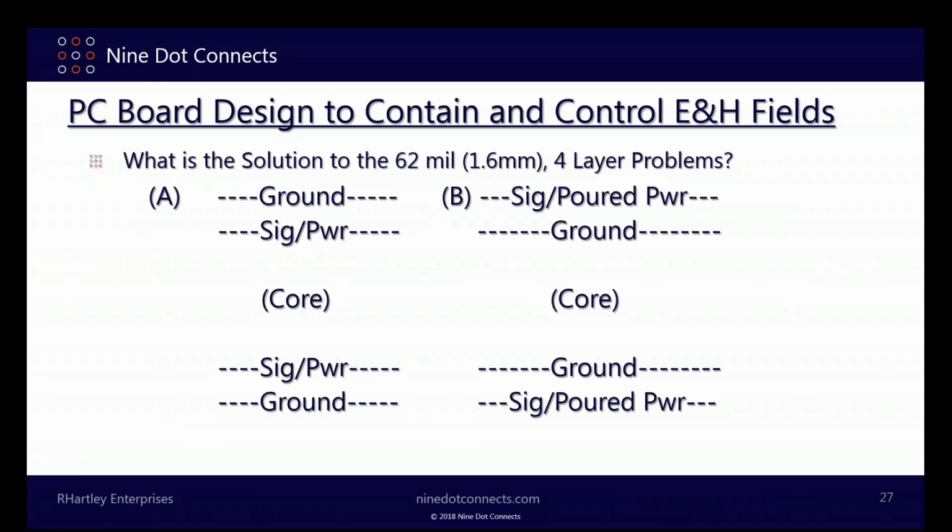The signals, because they're not trying to fight for space among the components, there was a ton of open space now on the signal layers because those pesky components weren't in the way, which left enough space for us to pour copper on all the open areas between signals on layers 2 and 3 and attach that to power. You don't need full power planes in a circuit board. You need power structures that create low inductance, because to achieve low impedance at high frequencies in a circuit, it isn't about how much capacitance is in the planes. It's about how low the inductance of those planes are.